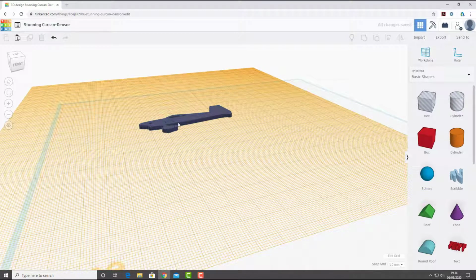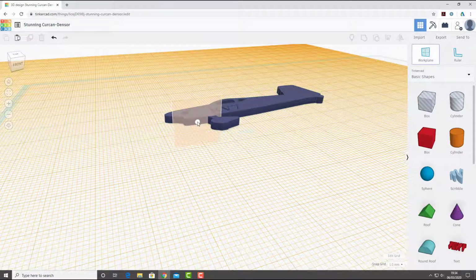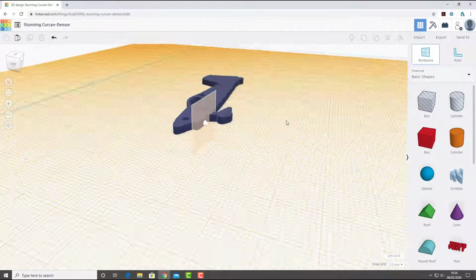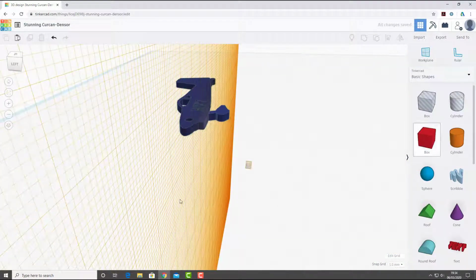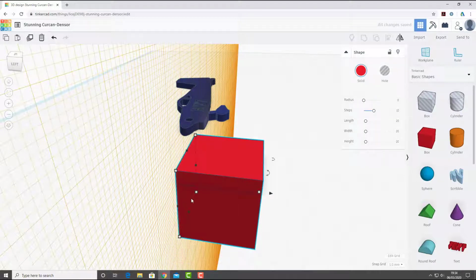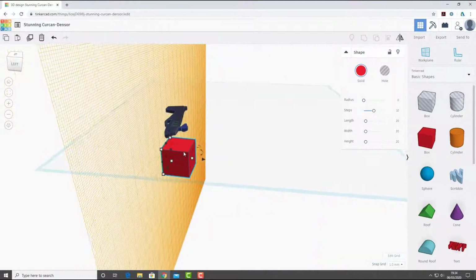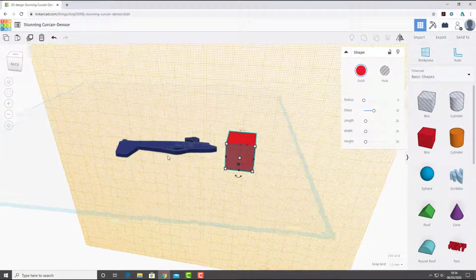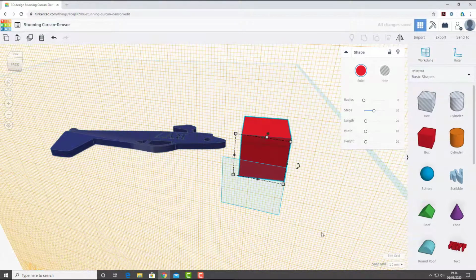It does make life easier when you want to put objects together in a certain way. Okay. Now, if you watch, you could put a work plane, it doesn't have to be horizontal. You could put a work plane like that, and then when you bring a box in, it will sit there. Okay, so as you can imagine, with a complicated assembly, you could use these work planes all the time.